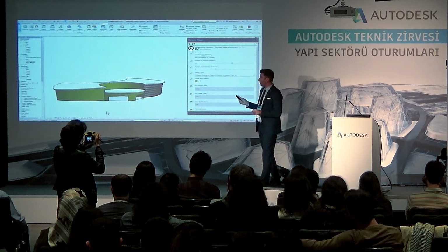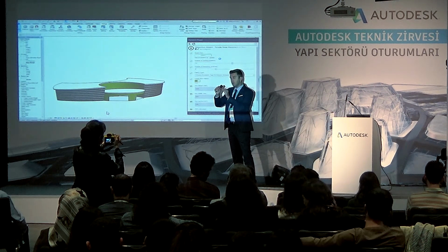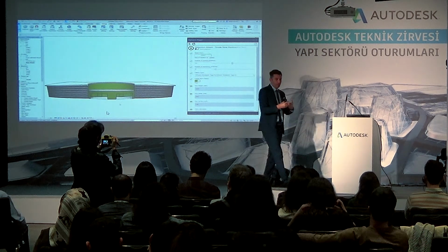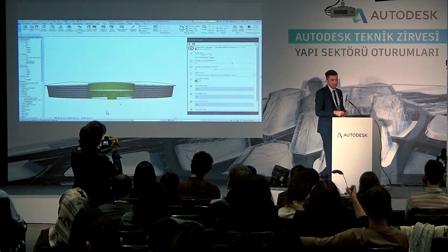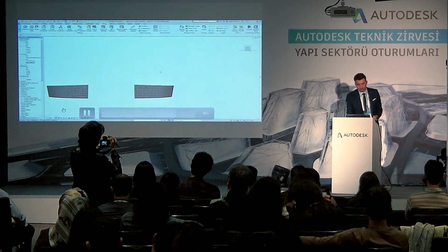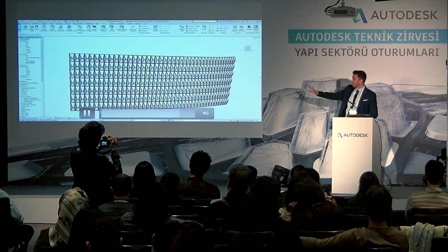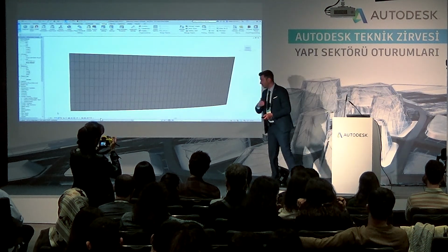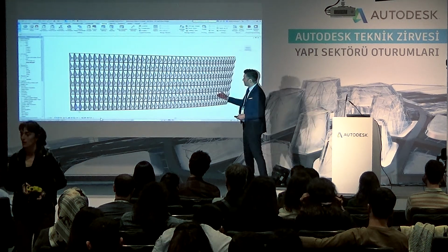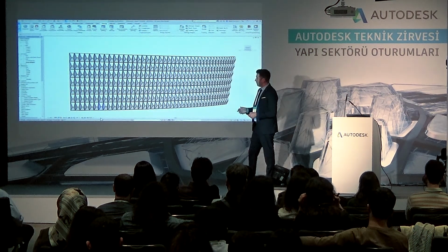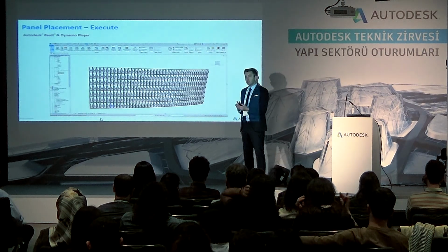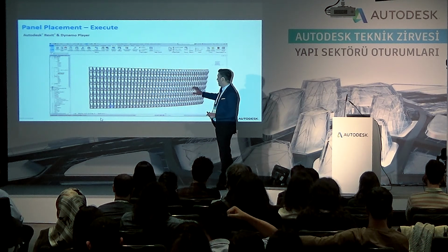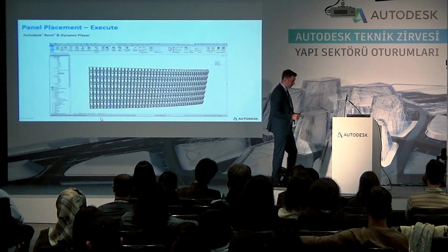So this is one click from Revit, we can just place the panels automatically. Basically, what we have done, we have made those adaptive families. We matched them to the same pattern of the conceptual layout of the facade using Dynamo. Of course, we can select another facade and we can add all those panels automatically. So we can place, in this case, hundreds of panels in one click, okay? And if we want to see only the shape of the panel, we can choose between different geometries. We can have just the rectangle, or we can have the full geometry of the family.